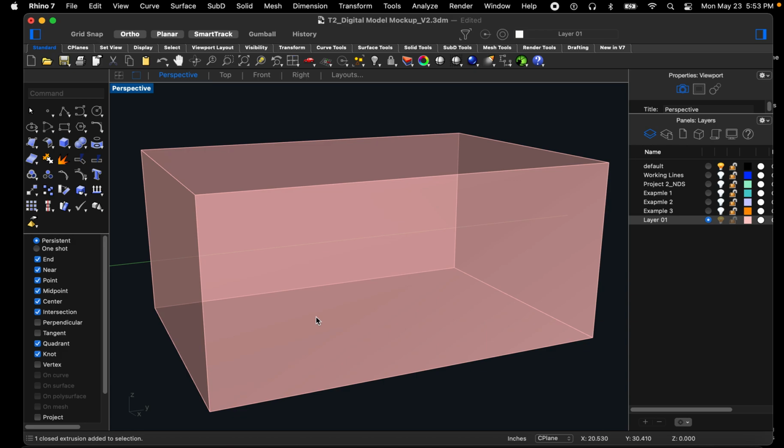Now, usually when we're modeling, especially if we're just trying to output a design, we're not worrying about watertightness or creating a closed polysurface. Usually that is not a problem. But as soon as we say, I need to 3D print this, okay, the 3D printing process is now being integrated into the geometry that we're creating. Okay, so the name of the game is a closed polysurface.